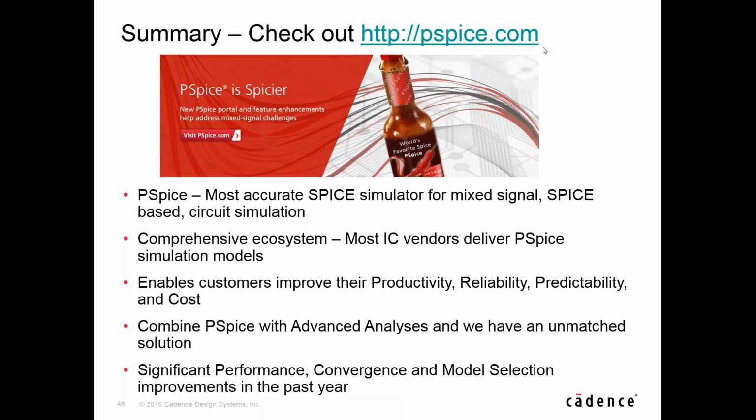Great. All right, we'll go through two more. One is, I need to simulate a noisy source in a time domain analysis. How do I do that? Another thing we did with the modeling app, in those sources that I've added, one of the parameters for specific sources is noise that you can inject into the source. And then we also have a standalone noise generator that you can add alongside your source to inject noise into your circuit.